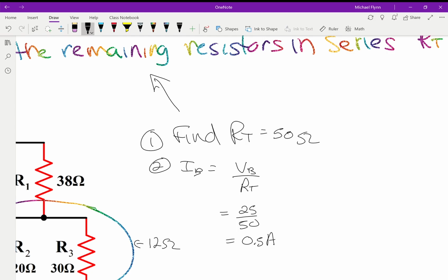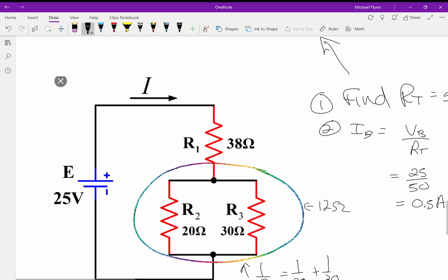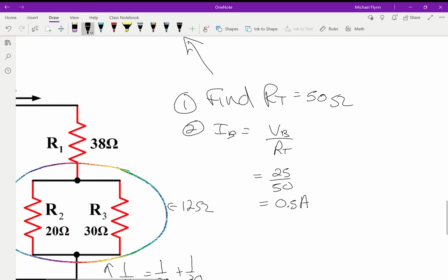Okay, now you have to think about this. Forget this letter E. This is how much current, that's I1, going through that first resistor, because if I get 0.5 amps coming out there, and then 0.5 amps comes back to it, well, everybody has to go through that first resistor before you get to this fork in the road, right? And so R1 and I1 has to be 0.5.